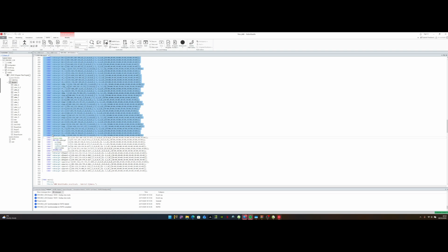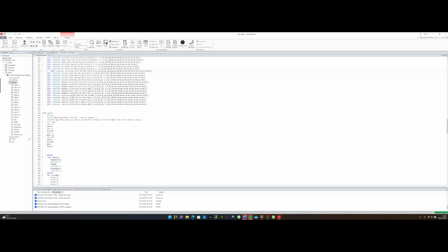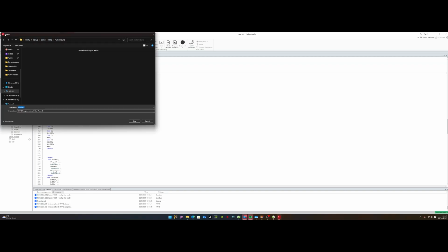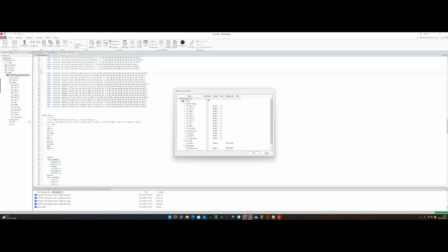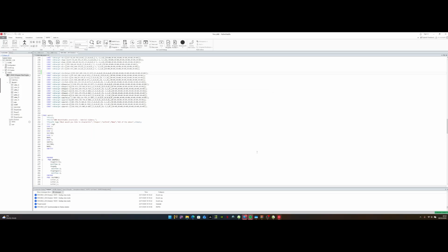So I can just delete them, that's fine. And now we have this. Now I need you to save. You essentially save by first clicking here, and now right click on it and synchronize back to the station. Select everything, click OK. Now everything is in sync.